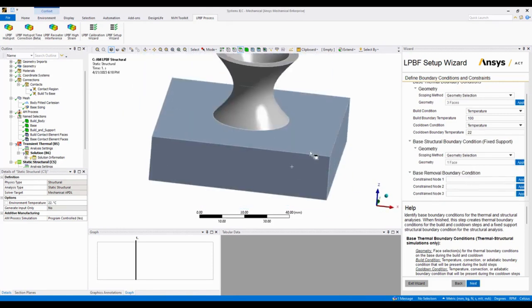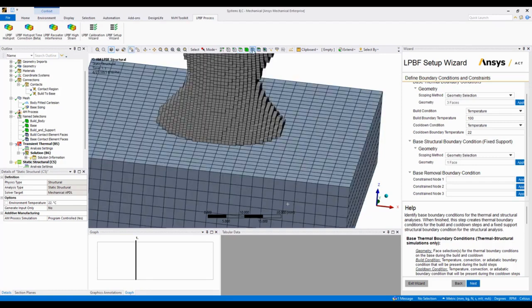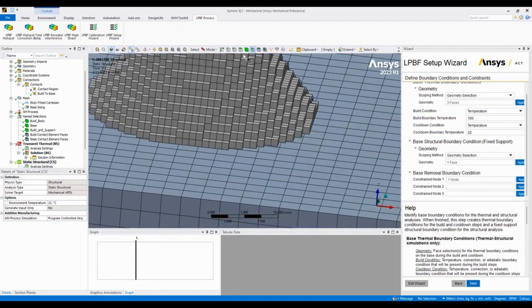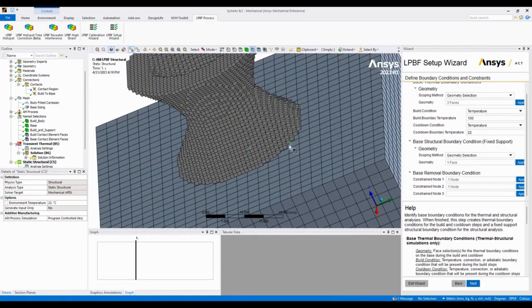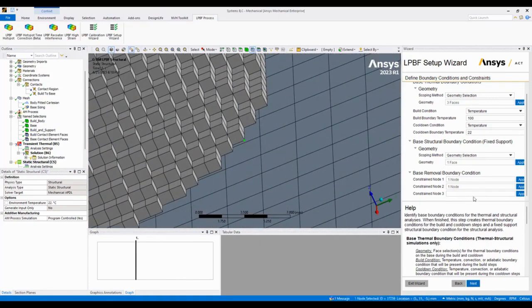We want to specify 3 points so that the part doesn't go fly off into space for being under constraint in a static analysis. So you can just pick any three nodes on the part itself. You can see when I switch to node select, I can pick the nodes that I want. So any node would do.